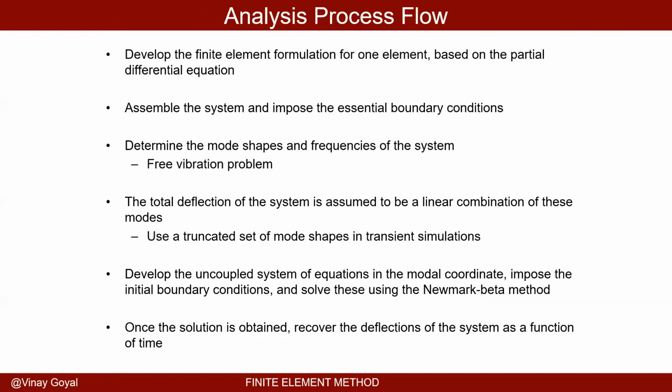So what is the analysis process flow you have to follow? What is it that you need to do? Develop the finite element formulation for one element using the partial differential equation, the equations of motion, of course. Assemble the system and impose the essential boundary conditions. You then determine the mode shapes and frequencies of the system for the free vibration problem. So no forces applied, just boundary conditions. That'll give you the frequencies and mode shapes. That's what I discussed in the previous lecture.